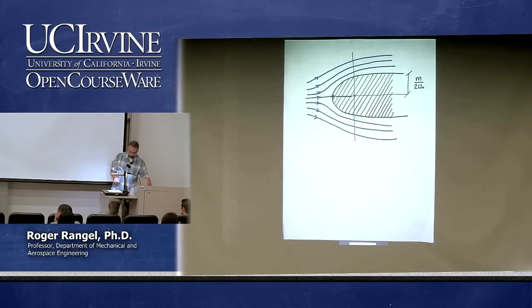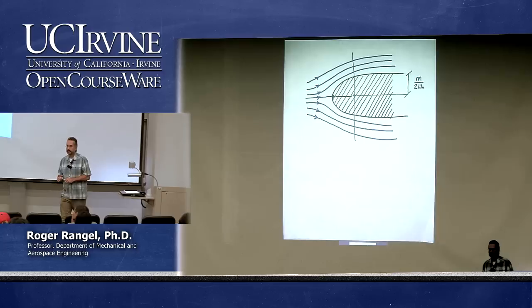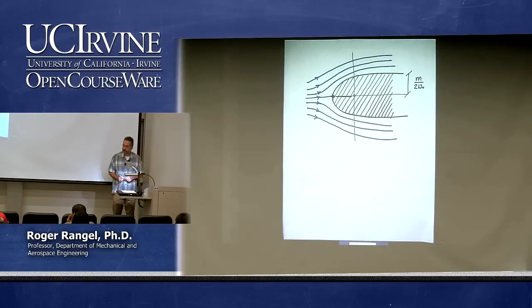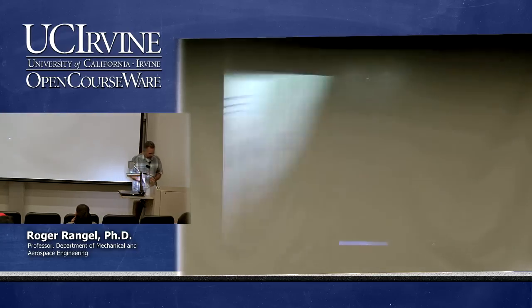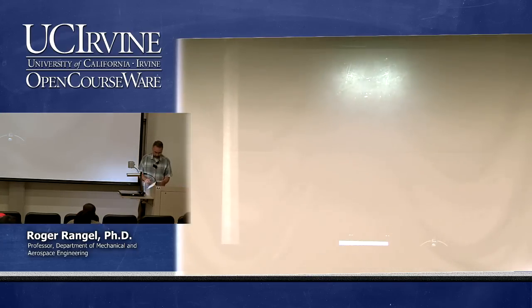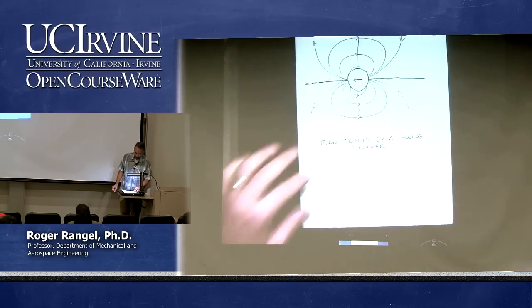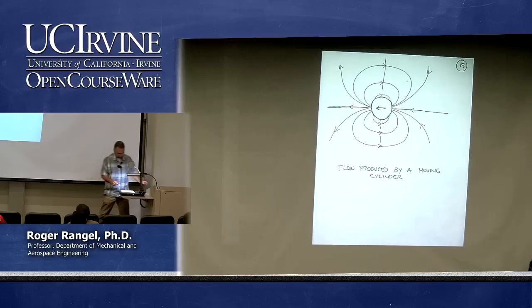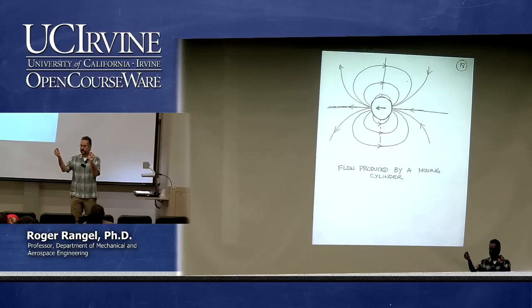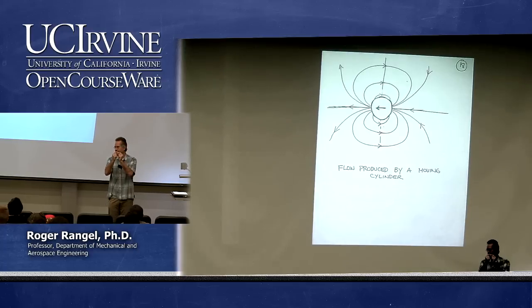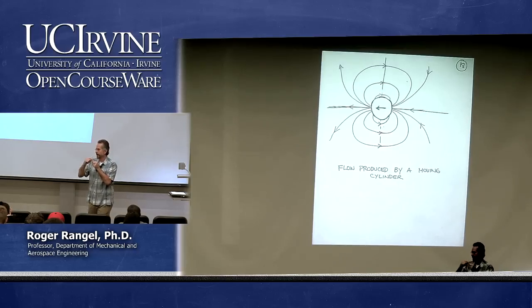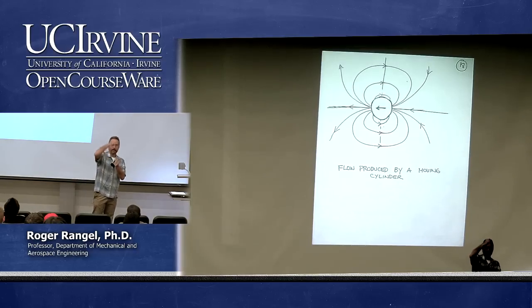Instead, what I'm going to do is show you how to create another important superimposed flow, which has very many practical applications in aerodynamics. And the way we're going to do that is we're going to start with the doublet. And you've seen this figure already before. The doublet, remember, we obtained by taking a source and a sink and putting them together at the center of the original coordinates, but we had to also increase the strength of each so that when they meet at the center, they don't cancel out, and that's how we got the doublet.